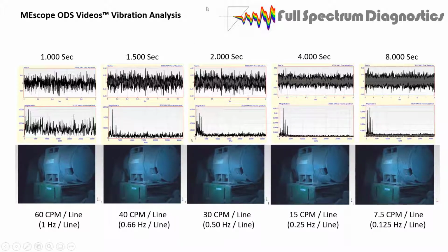The other thing that we're working on at Vibrant is ODS-FRF. The ODS here, or the discrete Fourier transform that we get, is fantastic. You can put your cursor on any peak, get the phase values, get the animation results you want, and it works really well. 2 seconds is probably the key feature in this. For the ODS-FRF, we're not limited to that. We can average and overlap process the signals and clean up the noise floor. So it might be that we could do the data a little bit faster, but we're still working on that. That's probably going to be in the next month's webinar. Pretty exciting signal processing stuff, though.